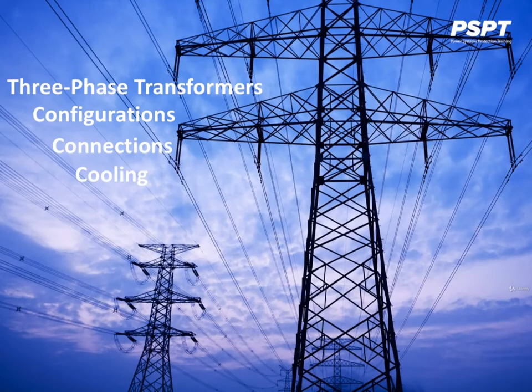Three-phase power distribution requires a lesser amount of copper or aluminum for the transferring of the same amount of power as compared to single-phase power. The size of a three-phase motor or generator is smaller than a single-phase motor or generator of the same rating. Three-phase motors are self-starting as they can produce a rotating magnetic field. The single-phase motor requires a special starting winding as it produces only a pulsating magnetic field.